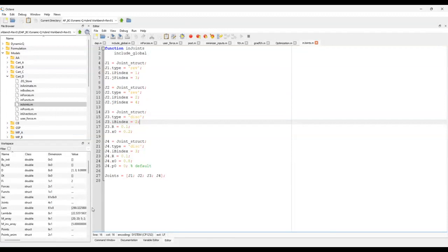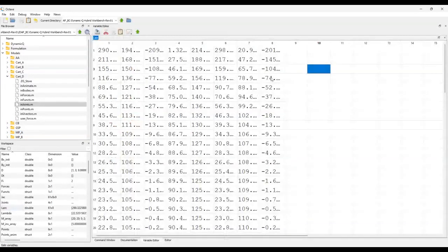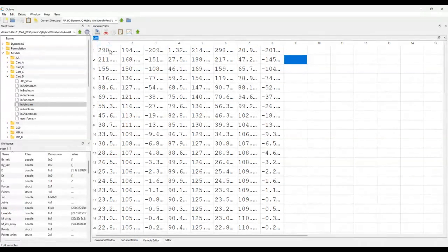If we go back over here, we see we have eight Lagrange multipliers. So it's 4 times 2 is 8. So there are two Lagrange multipliers or reaction forces associated with each of your joints. So this should have only one reaction force? No, I think it has two. Yes, it's because it's your upward force, and then I think there's also the frictional force, if I'm not mistaken. So you have an X and a Y reaction force.